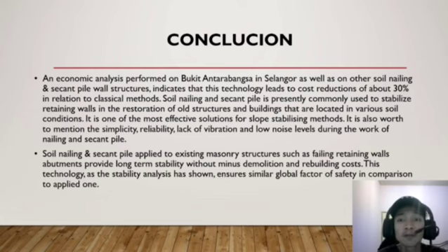Soil nailing and secant pile applied to existing masonry structures such as failing retaining walls and abutments provide long-term stability without major demolition and rehabilitation costs. This technology, as the stability analysis has shown, ensures a similar global factor of safety in comparison to the classical methods.